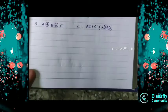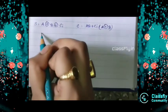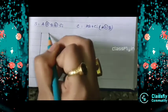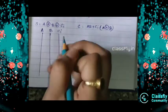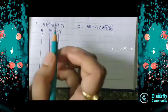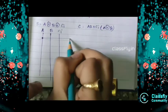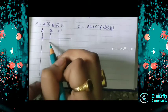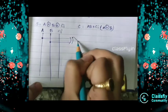So let's do it. So these are the two equations. First, do like this, make 3 straight lines. This one will be A, this is B, and this is Ci. First we will make the circuit for the sum, A XOR B. So I started this A and I started this B and I made an XOR here.